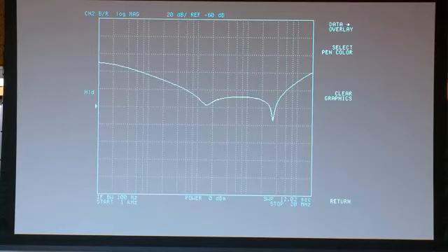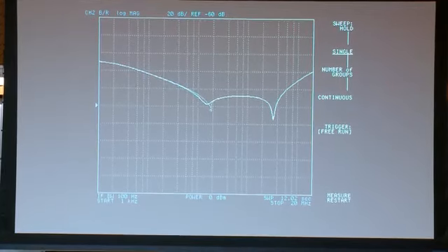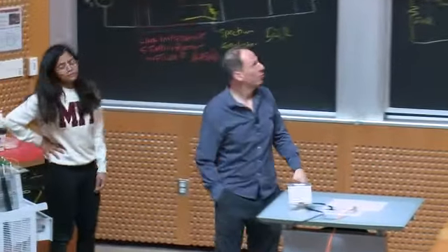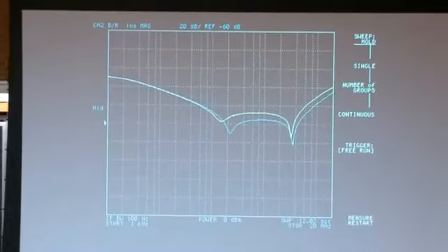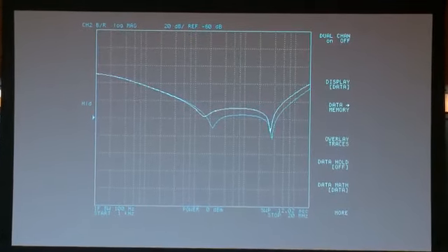The next one we're going to try, what we did was we said, okay, we're going to have an okay layout of the capacitor, so no parasitic inductance, or as little as we can get from the component itself, but we didn't fix the bad layout across the inductor. And so here we go. What you can see is, yeah, this is a little bit better because of what we got, but it's still terrible, okay?